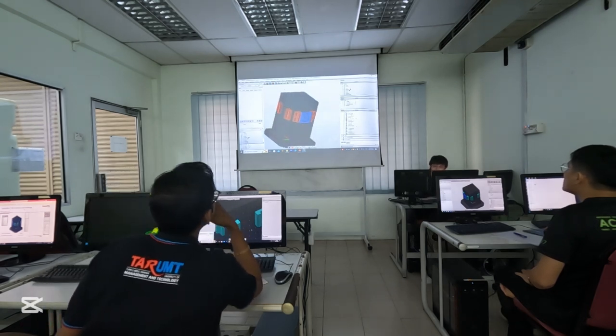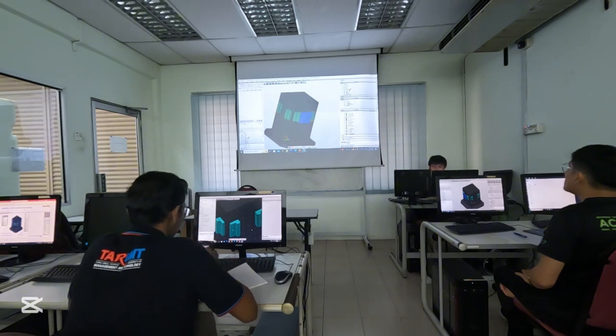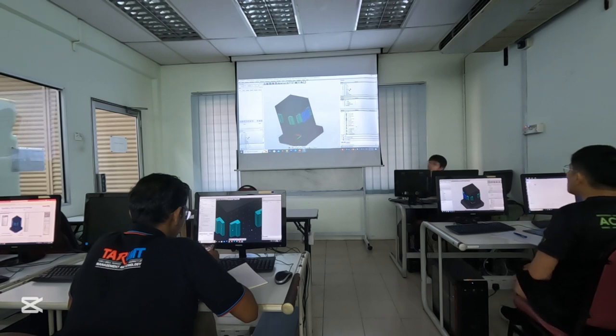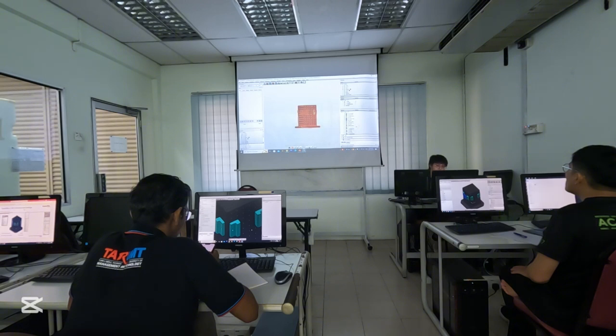This is by color, and another one is by layer. For this part, there are 3 layers: 1 is part, 2 is clamp, and 3 is tombstone. If I close the first one, the part, the blue color will not be on your screen. And when you select all and then open it back, it will not select what is not on your screen.